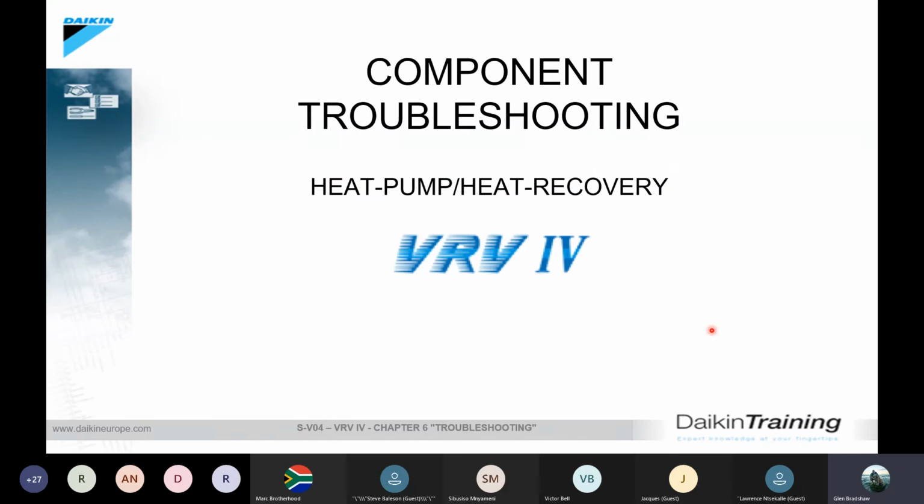All right, I've gone through that, and now we're going to start looking at component testing. On the subject of component testing, it's quite important. Some basics that you must have: you must be able to use a multimeter in the different functions, as in measuring voltage, resistance, and doing a diode check. I also recommend that you have good quality equipment and that equipment is in working condition.